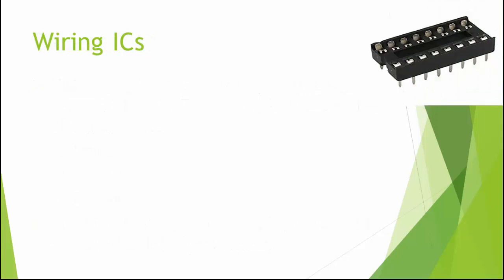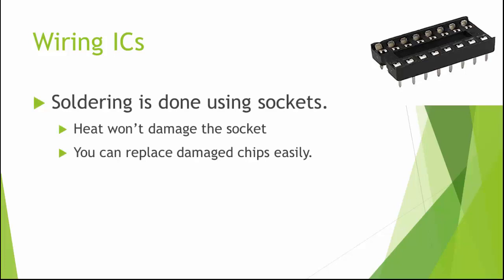Now, when we go to use that circuit, there are a couple little rules of thumb that will help us to avoid burning them out and help us to avoid breaking them. So if you need to solder your integrated circuits, don't solder them at all. What you do is you solder down one of these handy sockets. These pins can handle heat without getting damaged, but also if your integrated circuit wears out at any point, you'll notice that these spring clips hold in the actual chip. Well, you can swap out the chip without having to replace the entire device.